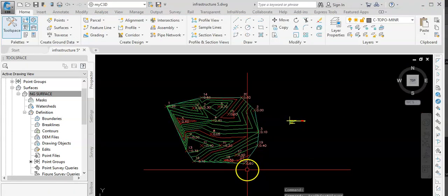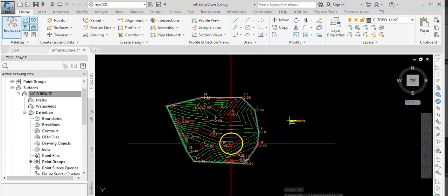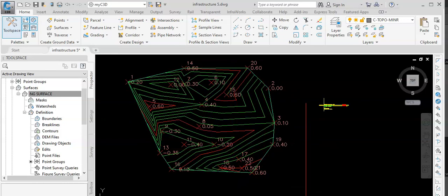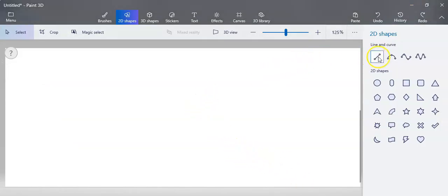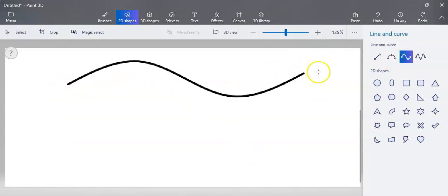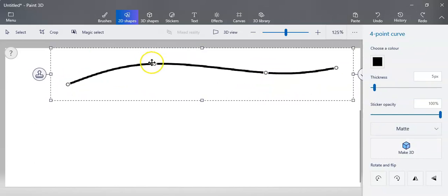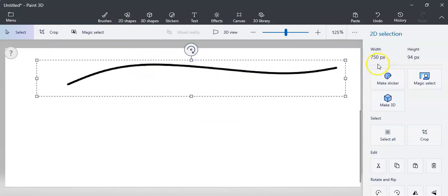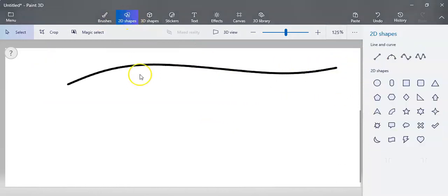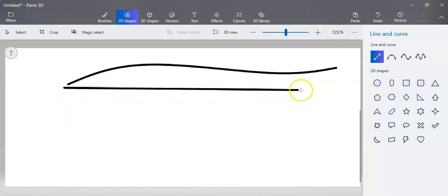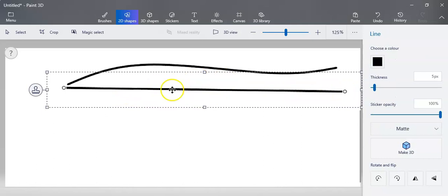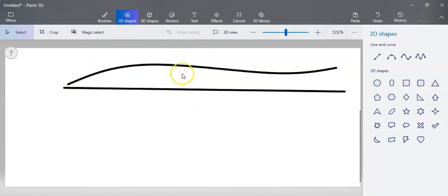To start with working out digitally the volume of the topsoil, first let's have a look in cross section at how we're going to achieve that. Let's say this is the terrain of the existing ground surface. It will be wrong to work out 150 from the ground surface not following the ground terrain, the ground profile. So it is wrong to work out something like that. But the right one is when we try to follow the same ground surface with 150. So the question is how are we going to achieve that?